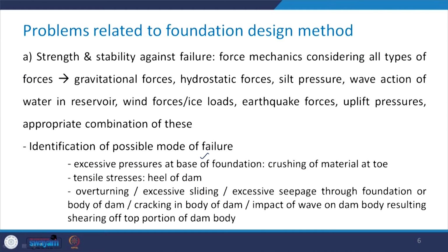The identification of possible modes of failure becomes very, very important. Now how can these occur? There can be excessive pressure at the base of the foundation, and that can result in the crushing of material at the toe. There can be the occurrence of tensile stresses at the heel of the dam, or there can be overturning, excessive sliding, excessive seepage through the foundation or the body of the dam.